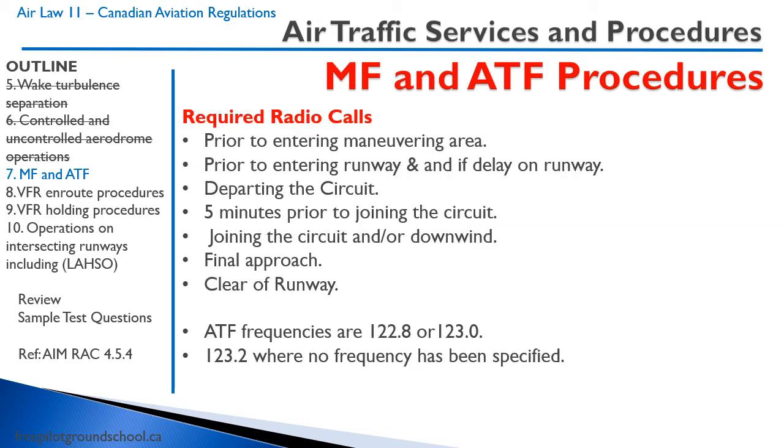Let's talk about these required radio calls. You have to make a radio call prior to entering the maneuvering area, so a taxiway or runway, prior to entering the runway, and if you're delayed on the runway, departing the circuit, 5 minutes prior to joining the circuit and or downwind, final approach and clear of the runway. The standard ATF frequencies are 122.8 or 123.0. You should memorize these. However, if there's no frequency specified, the frequency is 123.2.